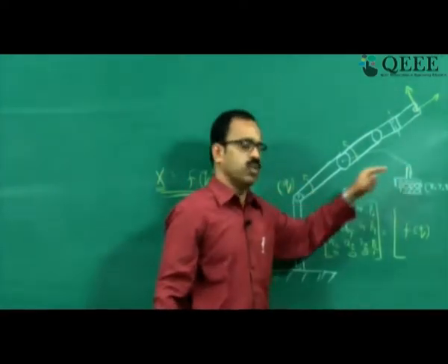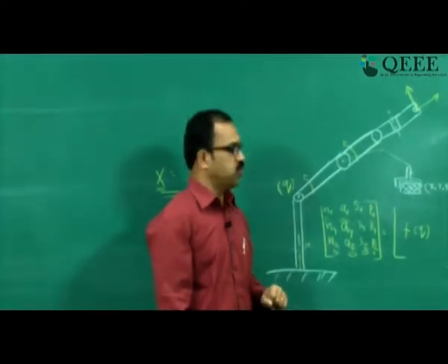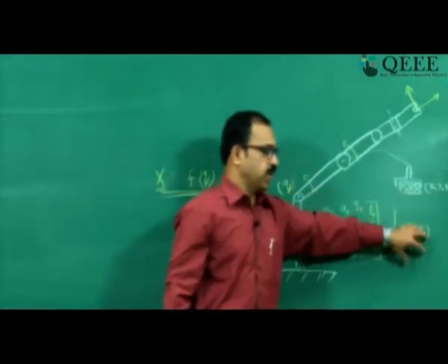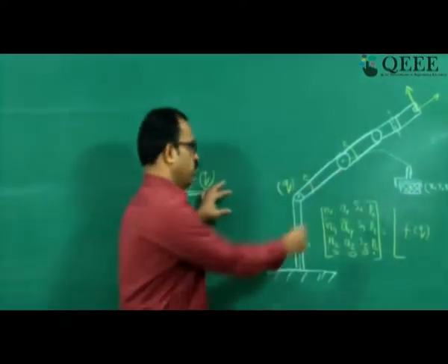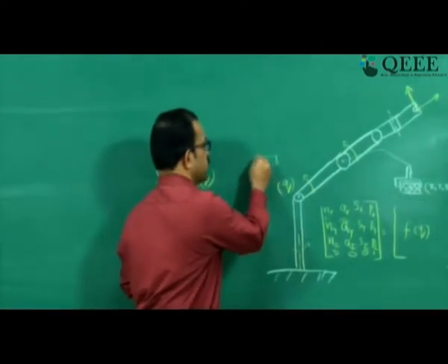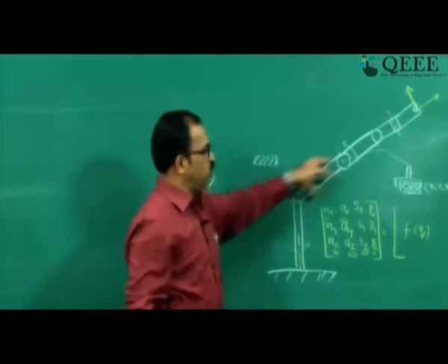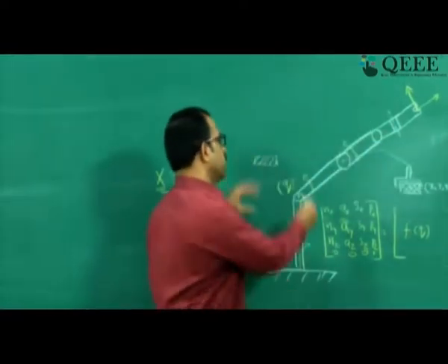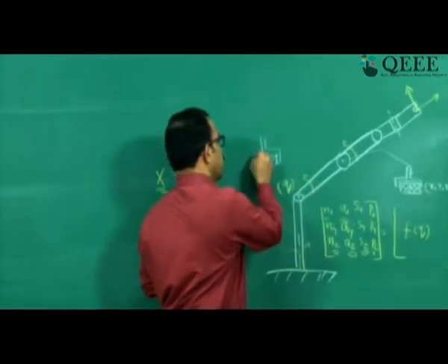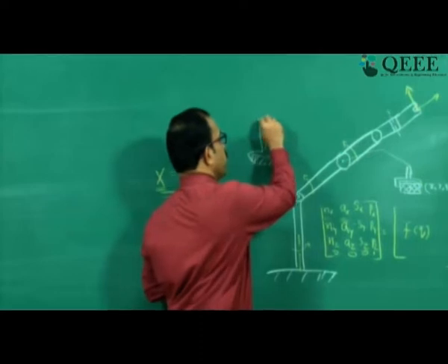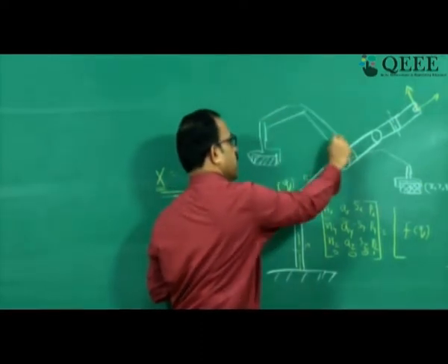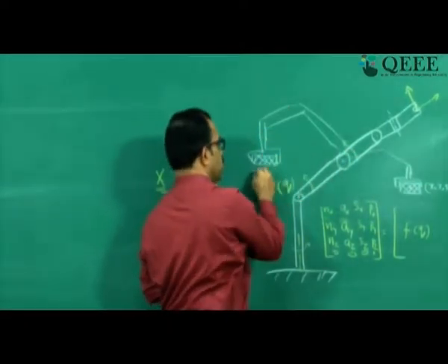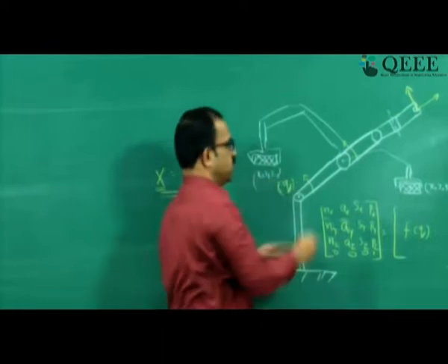That is basically what is needed in most practical applications of robots, because I want to pick up this object from a known location and place it at a different location. Now I need to place it somewhere here. So if it has to pick up from here, and then move from here to here and place the object, again the gripper should be in this position, and we need to know what the joint angles should be so that the robot comes to this side and places it at this position. Suppose this position is also known, x1, y1, z1, and this one is xyz.